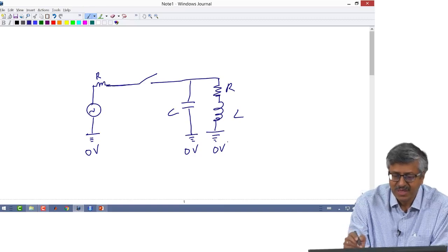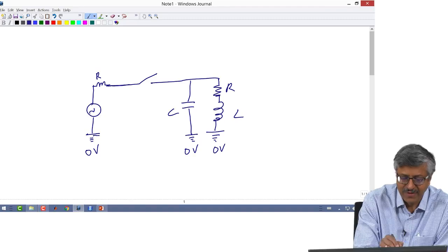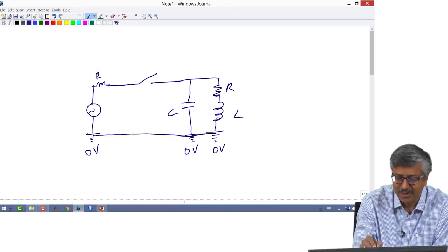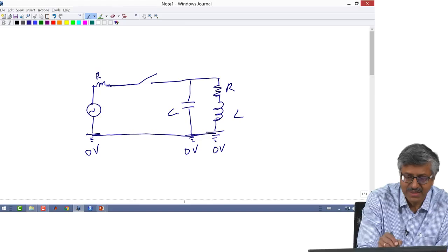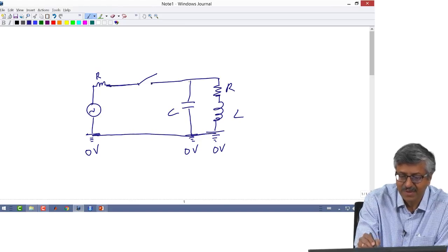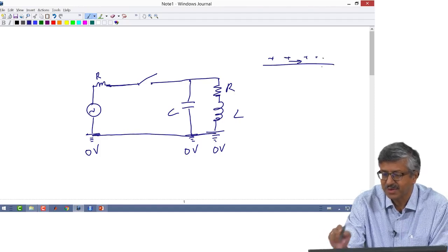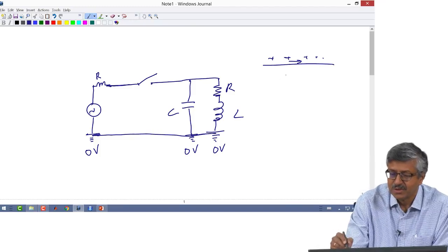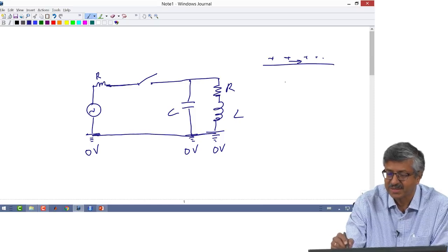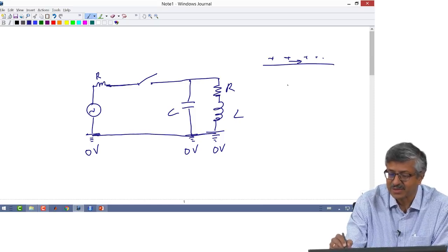But when you do this in practice, you have some sort of a track connecting all these grounds together, and that is made of a conductor. Similarly, all these components are connected together by conductors. So these conductors carry certain currents, and can have certain voltages in them. Due to that, it is producing some electric fields and some magnetic fields. So associated with electric and magnetic fields and the currents, and since these are not ideal conductors, you can have some resistance, some inductance and some capacitance.